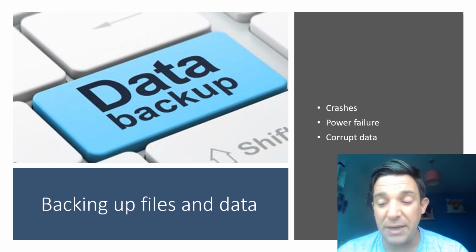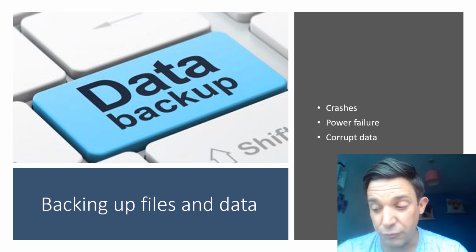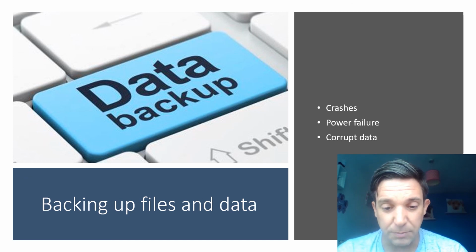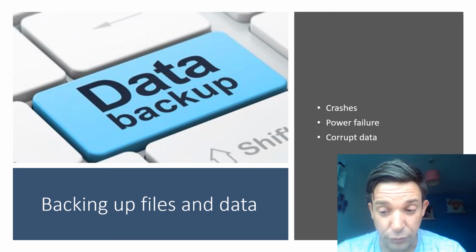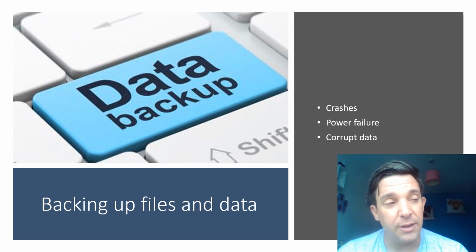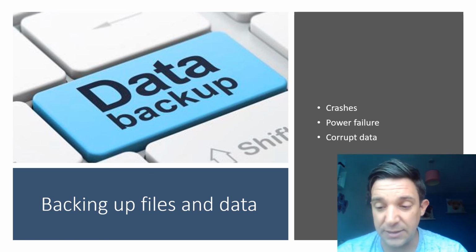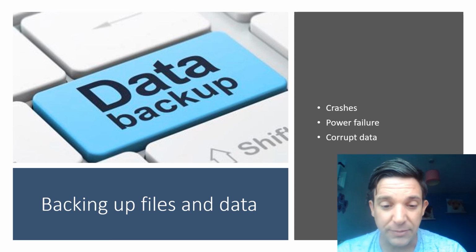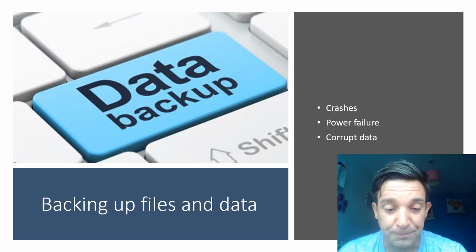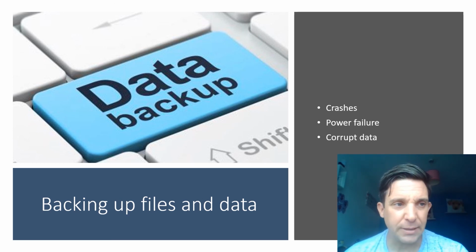The benefit of using a PDF to save a drawing file is that you don't need SolidWorks, you don't need the original models, you don't really need the original drawings, so you've got a date stamp. The negative of that PDF is that you can't edit it later if you should want to. Okay, so just remember, always back up and save your work.